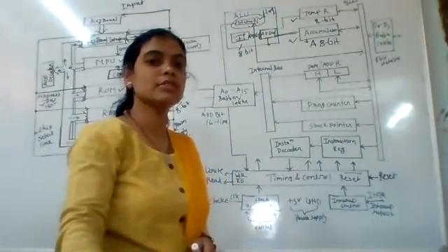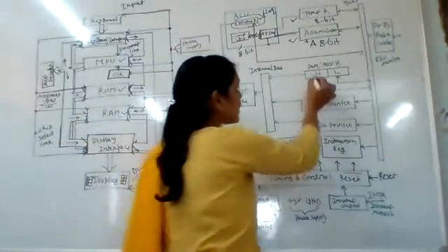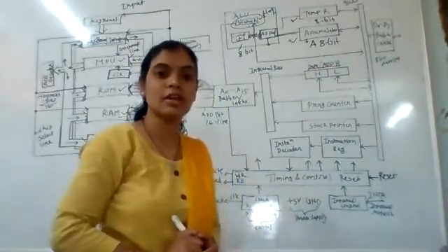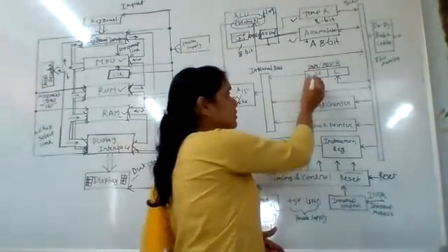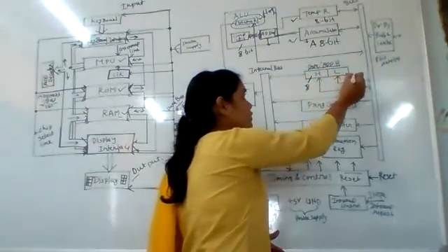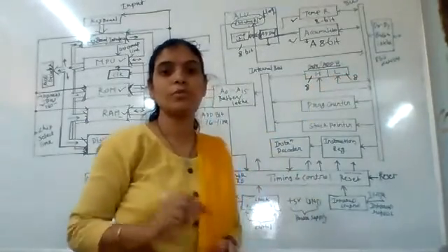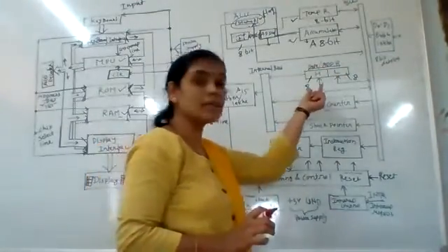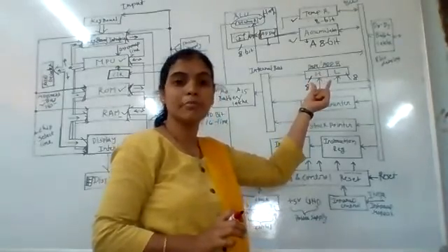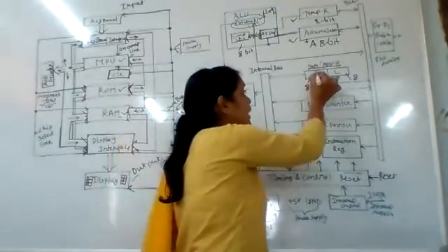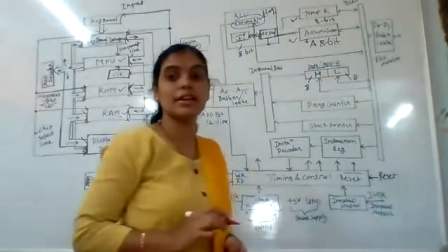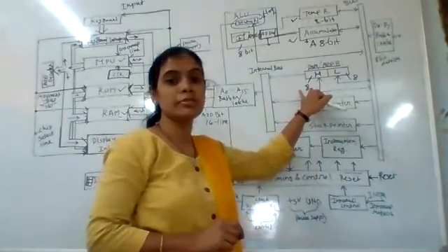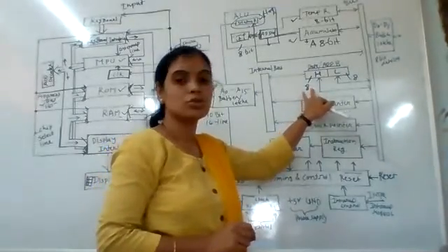Now next is the HL register, the data and address register. It is two 8-bit registers. H is 8-bit and L is also 8-bit. The data and address register is two 8-bit registers that can be used separately or as a combined pair. They are labeled H and L. Data is stored in this register, and when used as a pair, a 16-bit address can be stored.